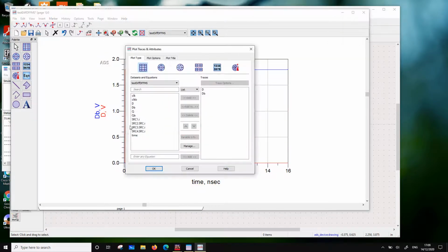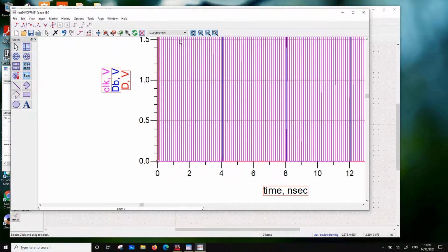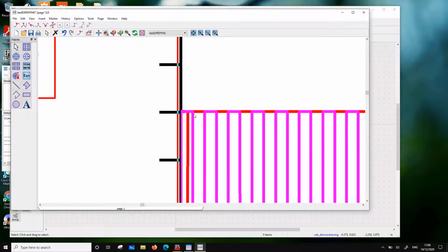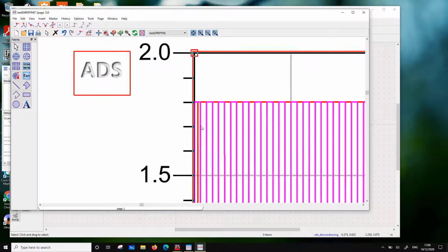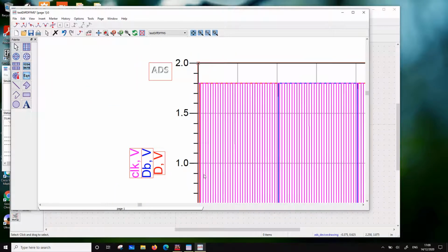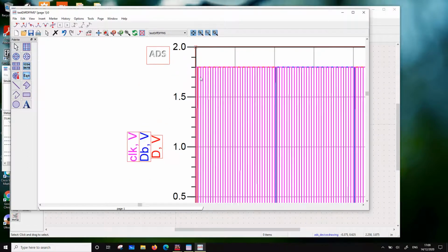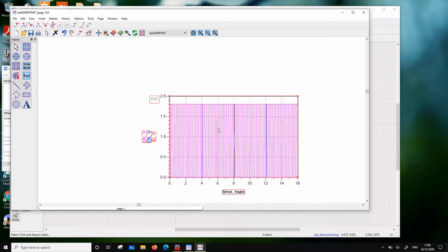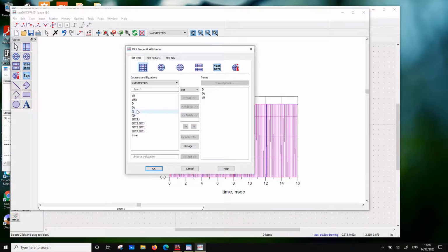So let's put here clock. Okay, so that's the clock, and I want to verify that this D transition has been delayed by 1/4 cycle here, right? So that means that the falling edge comes in somewhere here, right? So there will be an update on the falling edge. Okay, but then it will be read on the rising edge, so this might come low. So it might happen over here that you get a high. So let's check that. Okay, so I am going to put here a Q.